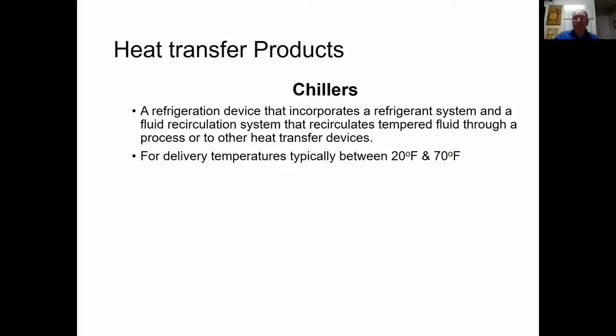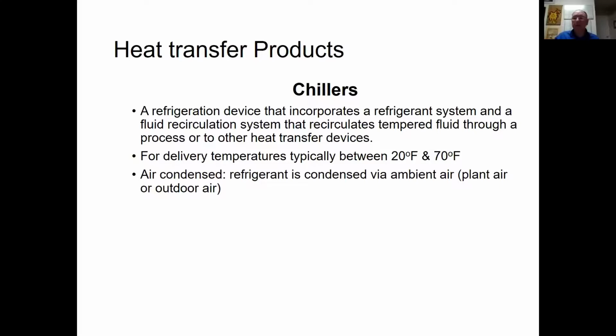50 degrees is the design temperature. In other words, a 10-ton chiller is rated at 10 tons at 50 degrees leaving water temperature. Anything below that, the capacity of that chiller is derated. Anything above that, you get a little bit more capacity out of that chiller.